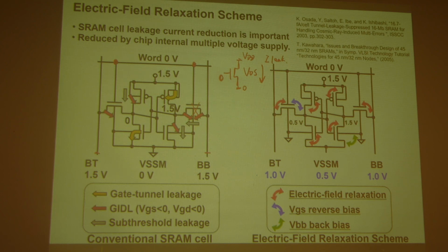So you can say that many transistors will have VDS like 1.5 volts. For example, if you look at this transistor, this storage node stores 0. Let's assume it's 0. Okay, that means the other one is 1, so it's 1.5 here. So this transistor, you look at the VDS, is 1.5 volts, right? So that means you have the leakage current here. And similarly, for this transistor, you will see 1.5 volts, because here this is 1.5 volts, this is ground. So you have 1.5 volts across that.